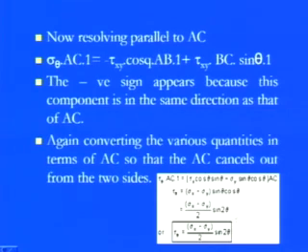So by applying two different stresses at mutually perpendicular axes, we can get sigma theta or tau theta at the oblique plane: (sigma x plus sigma y) by 2 plus (sigma x minus sigma y) by 2 into cos 2 theta will give you sigma theta, and (sigma x minus sigma y) by 2 into sin 2 theta will give you the tau theta value.